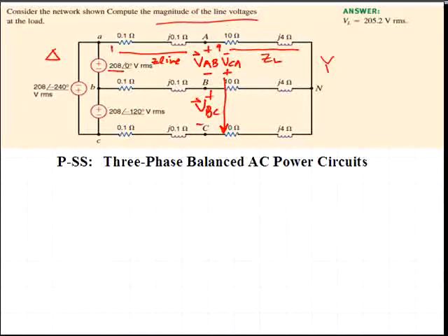there would be some voltage drop along the transmission line, so the line voltages at the load end would be less than the voltages at the source end. As indicated in the text, we should think Y, that is, convert a mixed system such as this, a delta connection and a Y connection, all to one equivalent Y circuit, and then we can work on a single phase of that Y circuit and solve for currents and voltages as necessary.